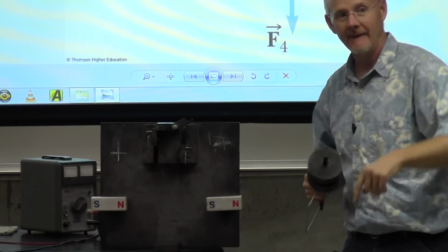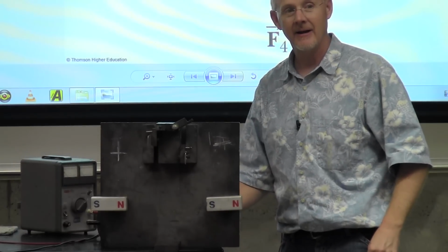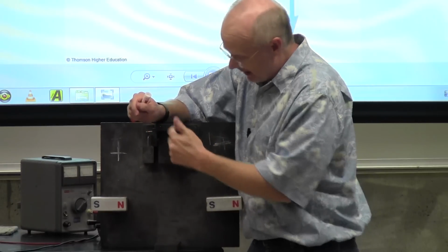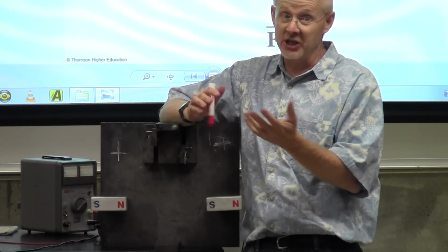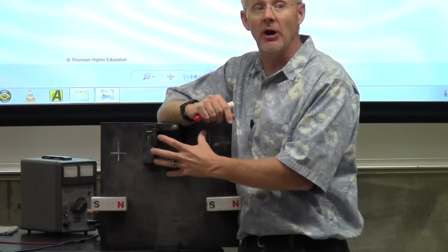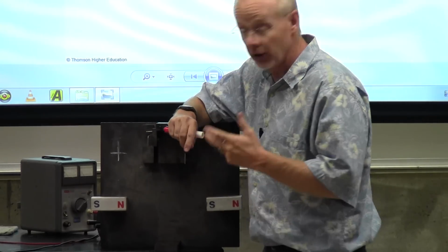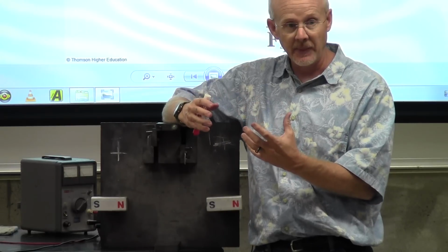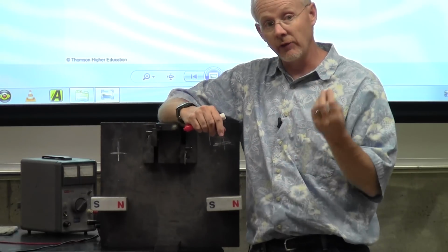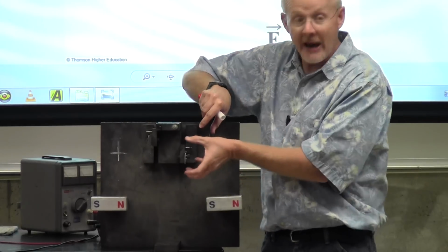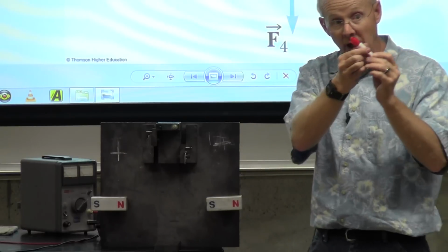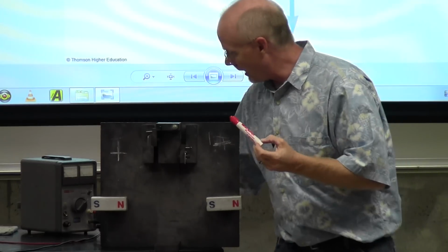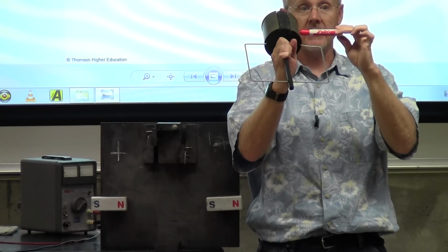How do they get around the contact not wearing out? Different approaches. This kind of homemade model obviously looks like it's going to wear out, right? You're going to see sparks flying. And when you ever look at a motor spinning, you'll see them. And like I said, I should bring a real motor. They usually make this out of graphite. And so the electricity flows through the graphite. And let's say this is the brushing. It's usually a long piece of graphite that is up against the commutator like this.